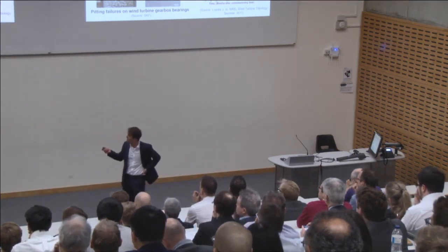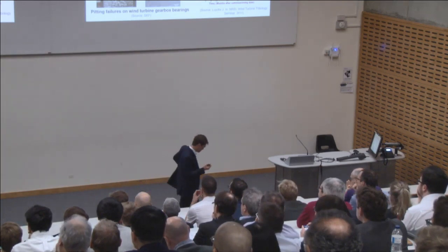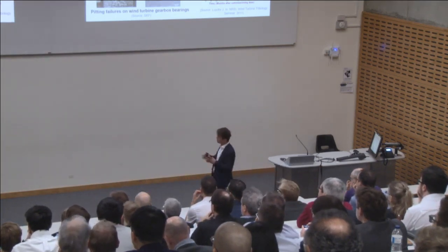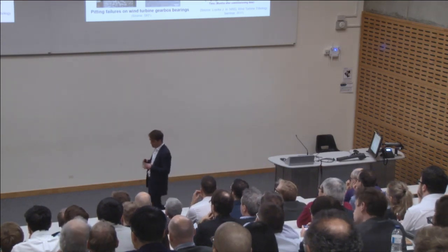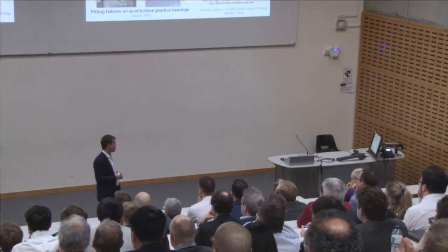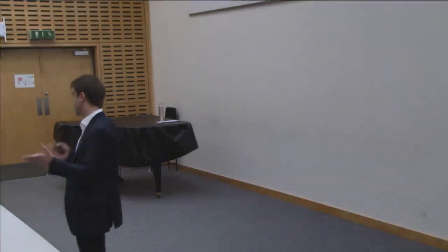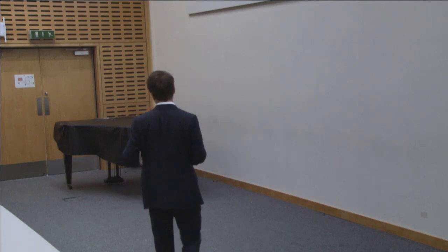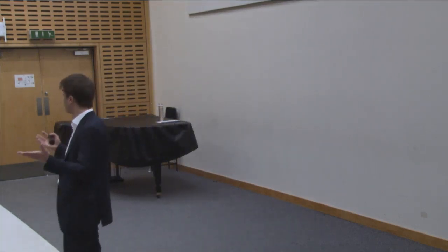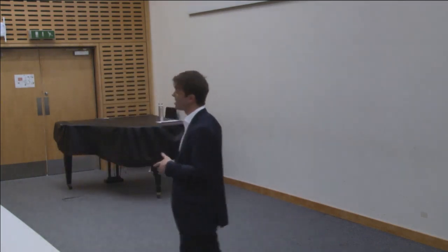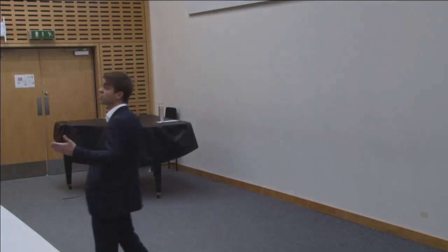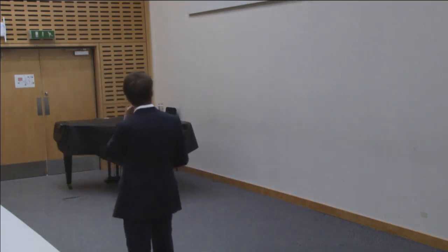If you cut those bearings up, in the subsurface, you see this nice looking, what we call white etching cracks, so widespread crack networks decorated by this microstructurally changed steel that appears white once you etch it and look at it under an optical microscope. So the obvious conclusion is we have these strange cracks, we have these early failures, these cracks must be causing the failures. We're doing a lot of research in this area, we don't have time to talk about it, but it turns out that actually they're not directly related to each other, but both are caused by a third factor, a particular stress sequence in time. That's one of our major ongoing areas of research.